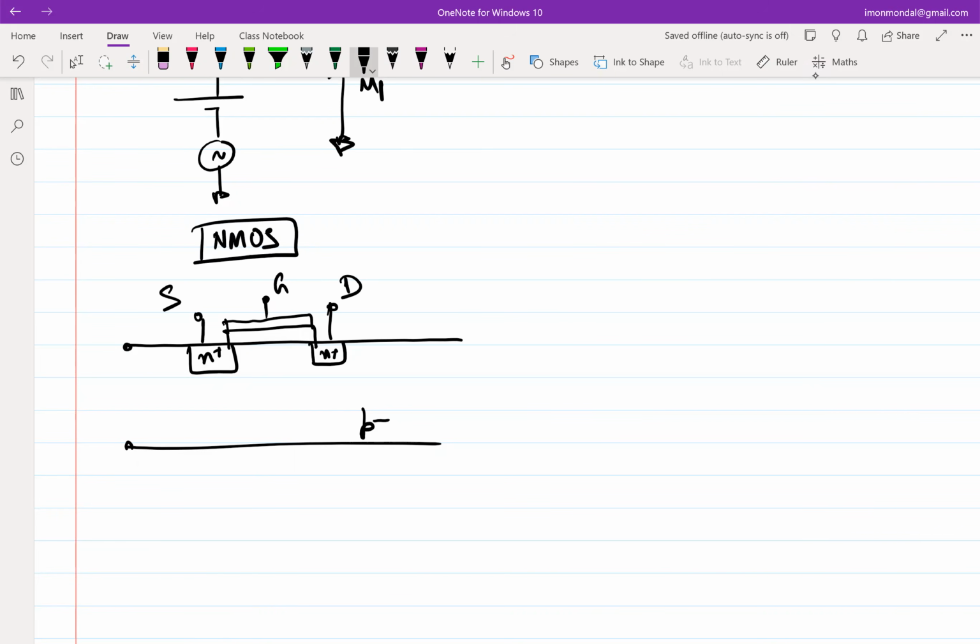The current flows from drain to source, basically by marking one as the drain and the other as the source. Internally I have assumed that the terminal marked as drain is at a higher voltage. So we saw that this will not work to make a current source at the top, which means that I want something which does exactly the opposite. And fortunately, we have that.